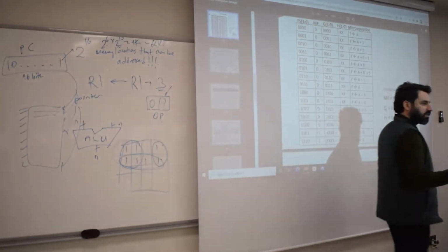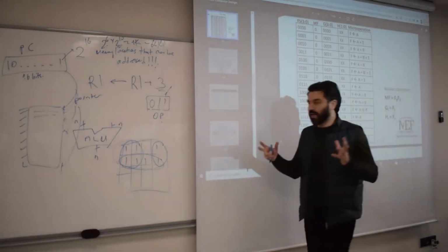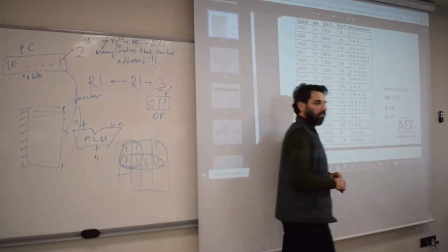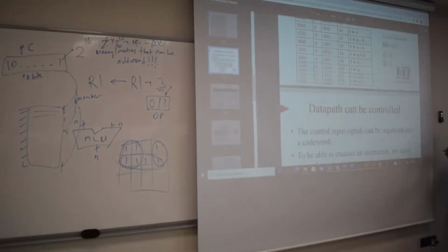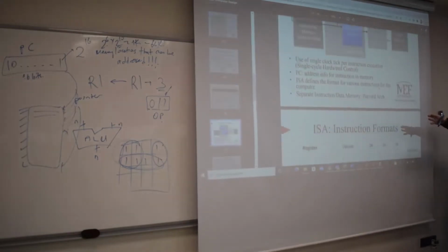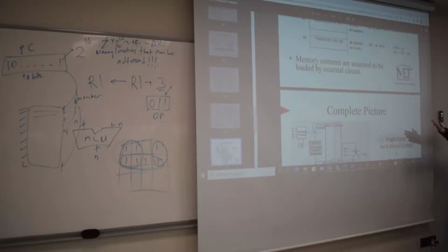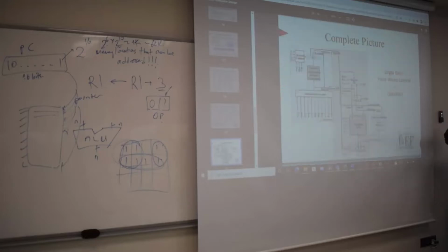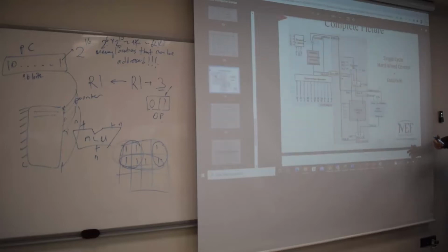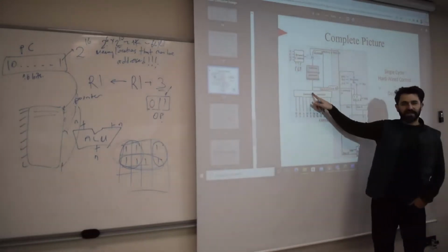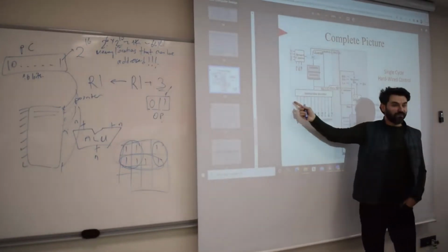That's why I'm saying that just adding a NAND gate will change your design, because your combinational logic design is based on these optimizations. An instruction decoder is a combinational circuit design. The only problem is that in our previous treatments of combinational logic design, there was only 1 output and 3 to 4 inputs, so it was a pretty easy input-output combination. However, in the instruction decoder here, you see 16 bits coming in, and each one of them is a function output. That means 20 different functions.